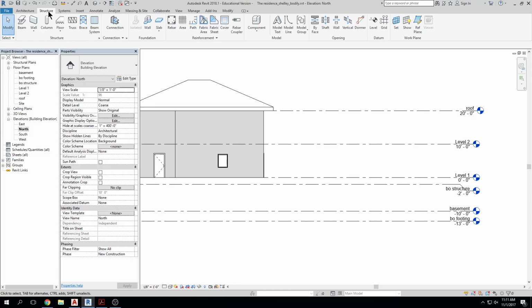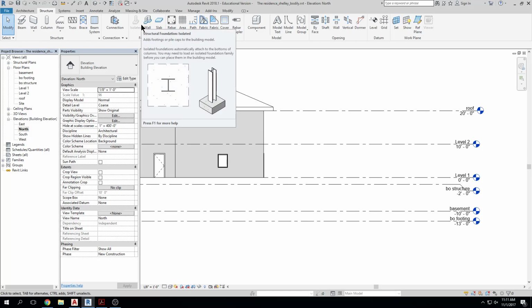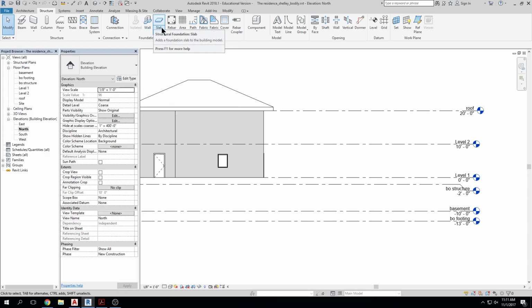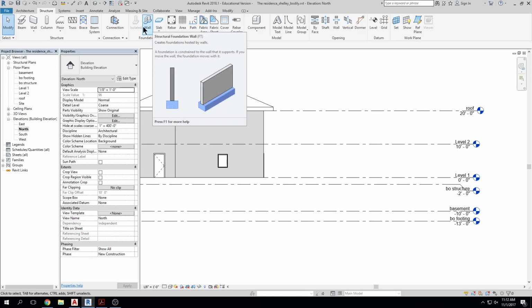When I use a structural element in here and you're drawing architectural drawings, it can be confusing as to who drew them, because it's a structural object. It's not an architecturally defined object. So if I filter out that object through my visual graphics, which is similar to my layering system, you could ask, well, who drew this? Well, it was the architect. Oh, but it's a structural item. Are you sure it wasn't the structural engineer? So there's some question there. That's one reason I tend to stay away from these structural objects, even though they're very easy to use, and we're capable of using them.